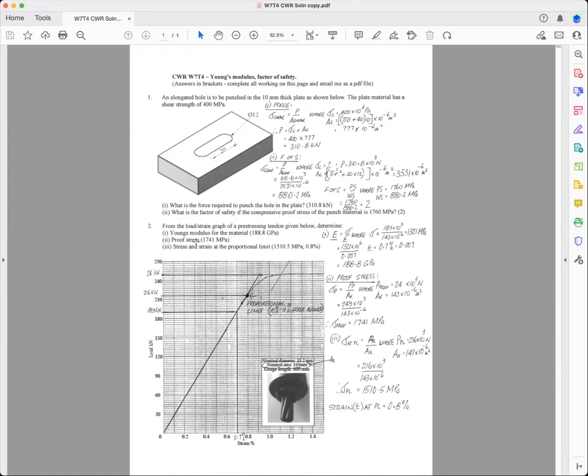Now, if you have a look at page 34, see that top diagram there? That's called a stress strain diagram that has a definite yield. Now, when I used to do tensile testing of wire material and bolt material, it always amazed me that when you reach the end of the straight line section, which is the limit of proportionality, with these metals that have a definite yield, you could see the metal still stretching, but the load going down.